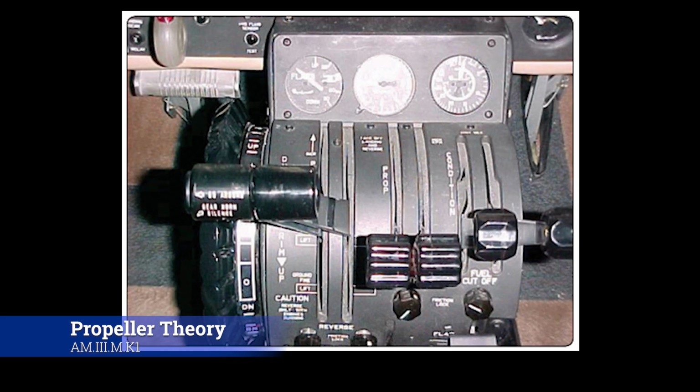Whenever you're checking a propeller's functionality, you're going to be in the cockpit, running, pushing this handle up and down and watching the manifold pressure come up and down. You'll also hear the sound of the propeller change drastically. You'll be able to hear an aircraft that's running up, going whoosh, whoosh, whoosh, as the prop goes through the different angles and produces different sounds. But inside the cockpit, you're looking at manifold pressure. That's what really shows you how much pressure the blade is producing.